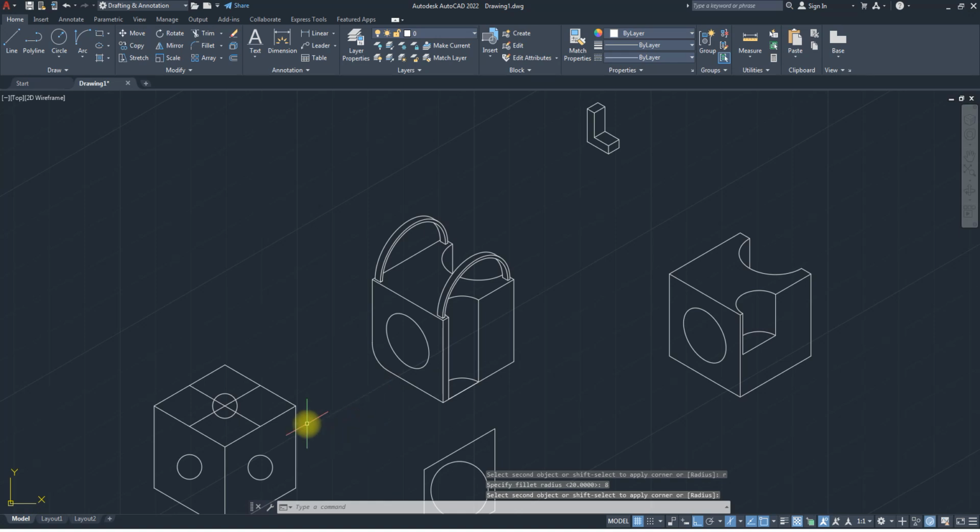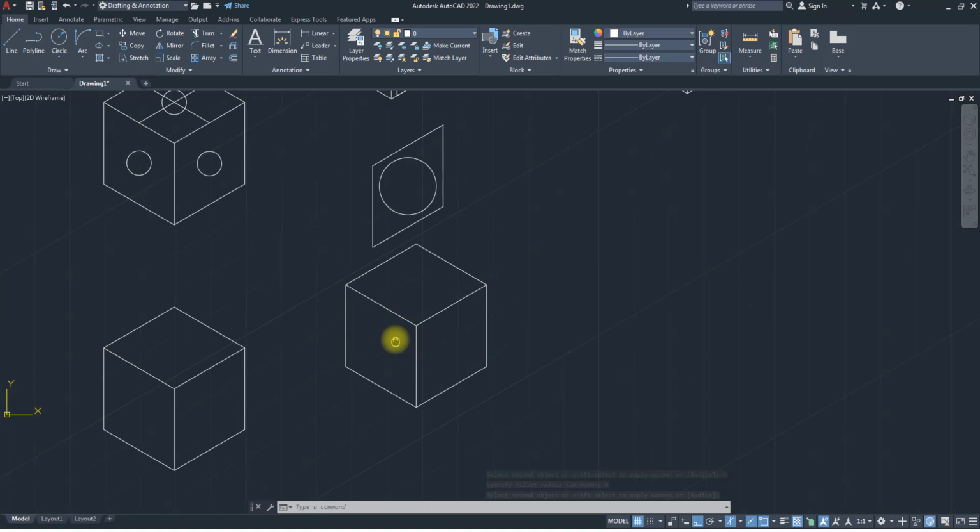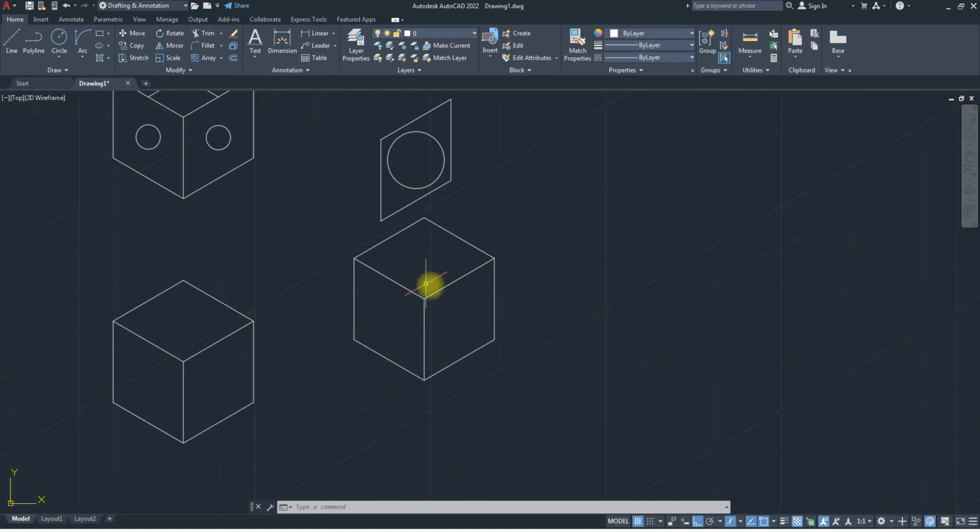Do you get that? So anytime you are filleting this kind of view, in this case, so if I run my fillet command and I set my radius to be 10, if I pick this, I pick this, I'll do the same thing, pick this and this. This line has to go. I hope you know that. And if this line is going, you need to show a line that shows that this line continues and it stops somewhere. At least this line stops somewhere and the curve starts at some place. So you need to use a line to show where the curve starts.